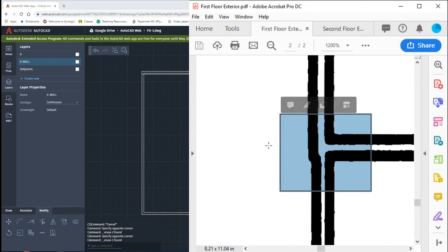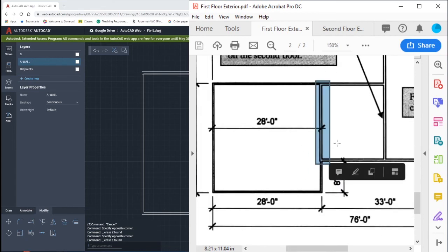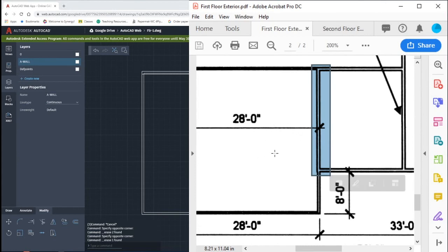Similar to the basement, this right edge just continues straight up from the outside. Now this wall is a little bit thicker. It happens to be 6.5 inches. The reason for that is to keep the cold air from the garage from entering in the home. We could put in more insulation in here. And so we need to start our wall down here at this bottom location.